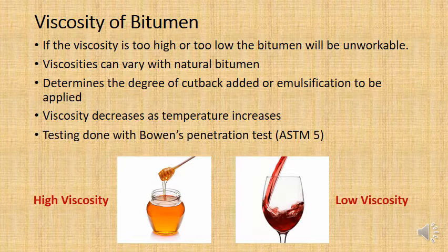Now, the other thing you need to know is that viscosity will actually decrease with the temperature. As the temperature goes up in the summer, the viscosity of the bitumen will decrease. The bitumen will get more runny. So some of you may have experienced this. Have you ever gone for a walk on an asphalt road in the real heat of summer when it gets really hot? And the road sort of gets sticky because the bitumen has lowered in viscosity and it's sort of become liquid. You've got this sticky bitumen on top of the road surface.